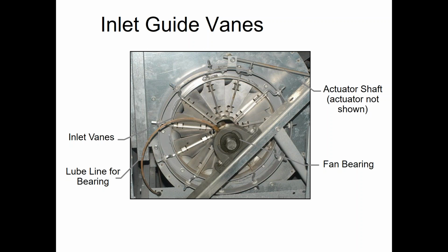All right, from a static pressure standpoint and an airflow standpoint. So I have this duct system providing me this cold air all the time. And then I have these dampers that are going to throttle back in the duct in each individual zone to give me less of that cold air. So when those dampers throttle back, the static pressure in the duct system is going to build up because they have too much airflow for the amount that I want to use.